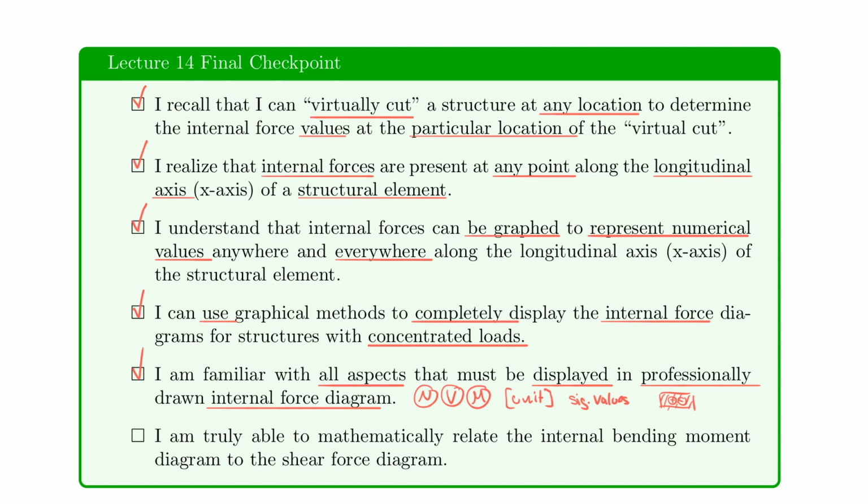All right, and then last but not least, it's very important that we understand that we can mathematically relate the internal bending moment to the shear force. And this can go to much higher levels than what we talked about today. And we will actually talk more about this in the future in this class, but this goes way beyond the purpose of this class. Engineers deal with this a lot later on for different engineering designs. Please remember, though, for now, that we introduced the concept that the shear force is really dM/dx. So it's the derivative of the moment.